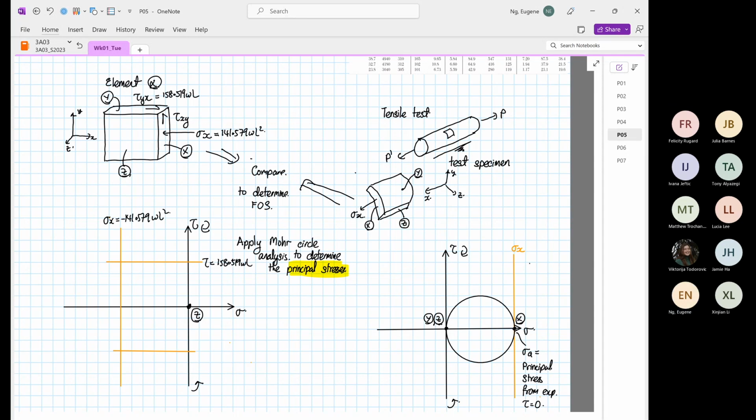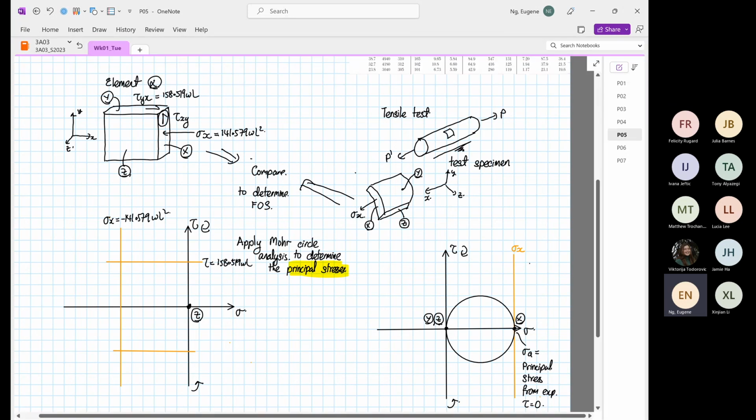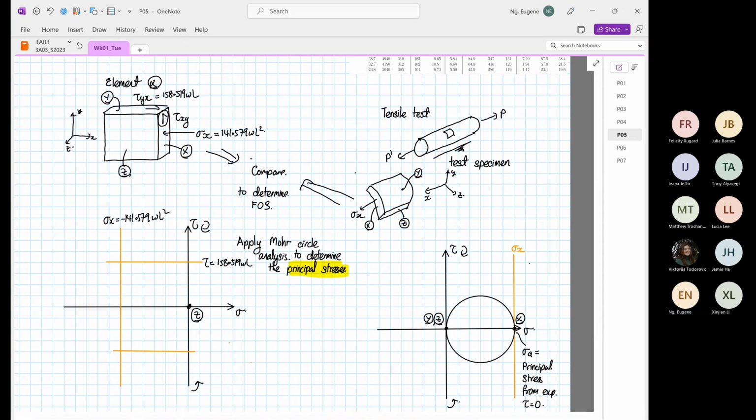Okay. So if we use Mohr's circle criteria, bear with me, I will just take 5 more minutes, okay? So when we draw Mohr's circle at point X, this is our X line, the extreme orange line. And if you look at this over here, it will rotate the element in the anti-clockwise direction, right? So this is our point X. And over here, this is our point Y. Point Y has 0 normal stress. Okay, that's our point Y.